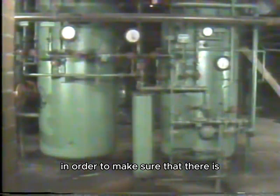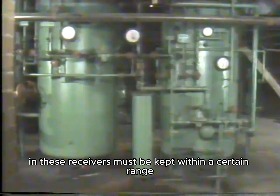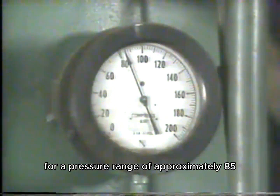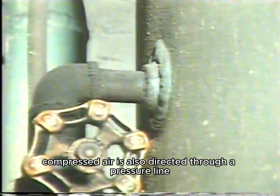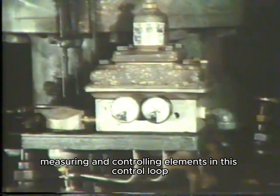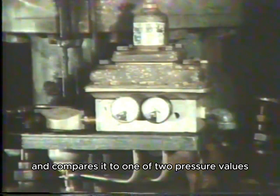In order to make sure that there is enough compressed air to satisfy the requirement of the equipment in the plant, the pressure in these receivers must be kept within a certain range. This system has been adjusted for a pressure range of approximately 85 to 100 pounds per square inch. In addition to being directed to plant equipment, compressed air is also directed through a pressure line to an instrument like this one, which we'll refer to as the controller. Although we call this a controller, this instrument performs the functions of the sensing, measuring, and controlling elements in this control loop. It senses the pressure, measures the amount of the pressure, and compares it to one of two pressure values.